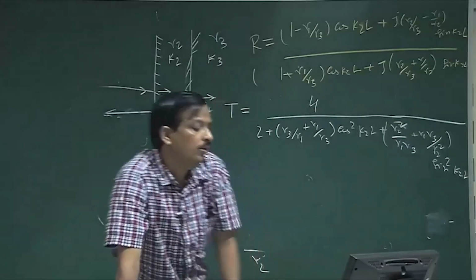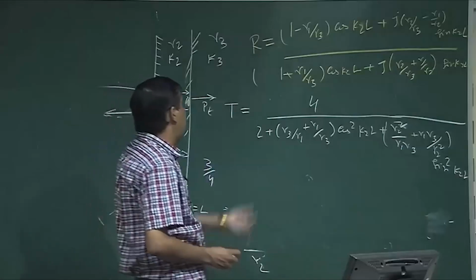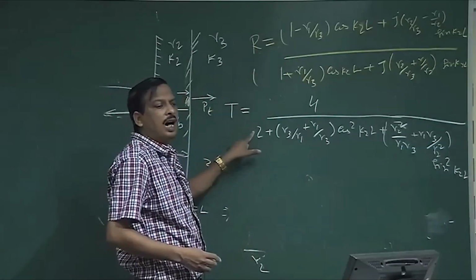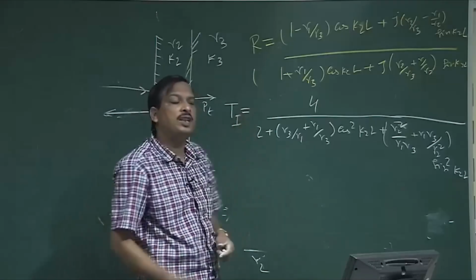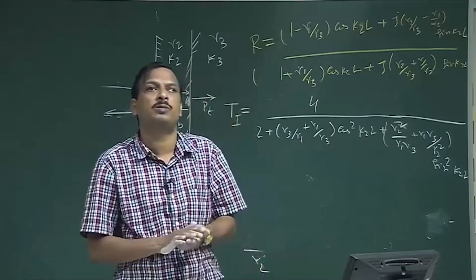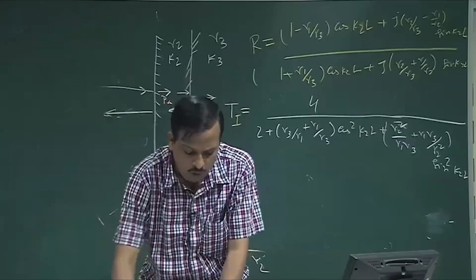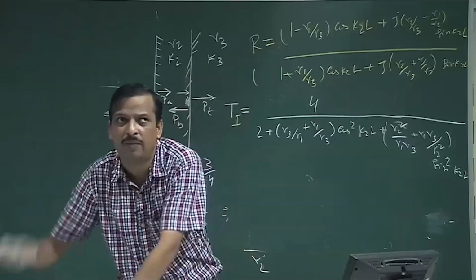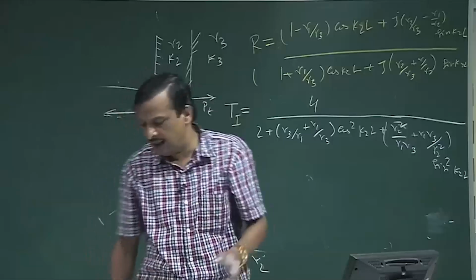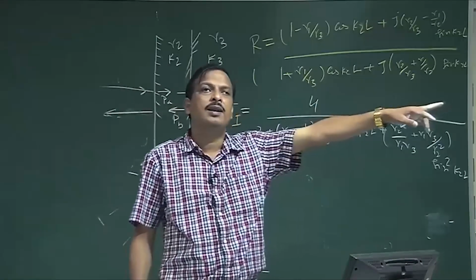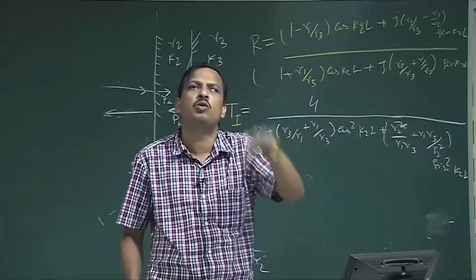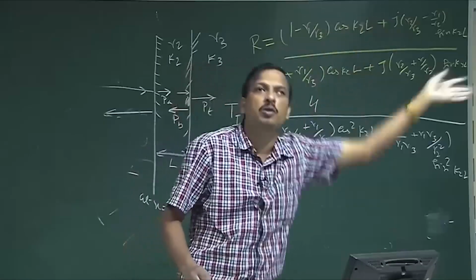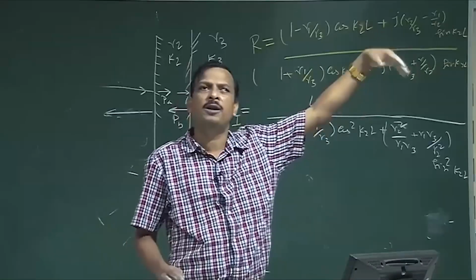Okay. Last class we derived the expression for Ti, the transmit intensity coefficient for sound transmission. What we want to know is this: suppose I place a box in this room and there is a wall of thickness L, how much acoustic energy from this room will be transmitted into the corridor?